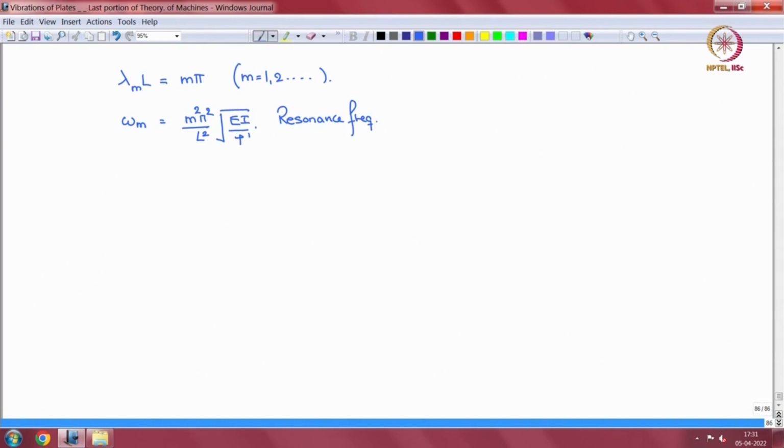Okay. And the mode shape as before ends up looking like u3m of x is equal to, it looks very simple, 1 over lambda_m du3m/dx at 0 times sin(lambda_m x). Or we say some amplitude A_m sin(m pi x by L).